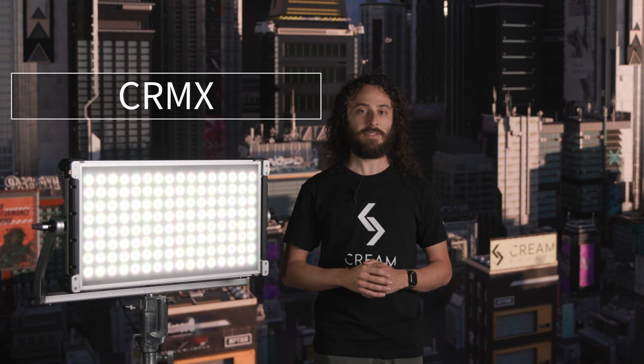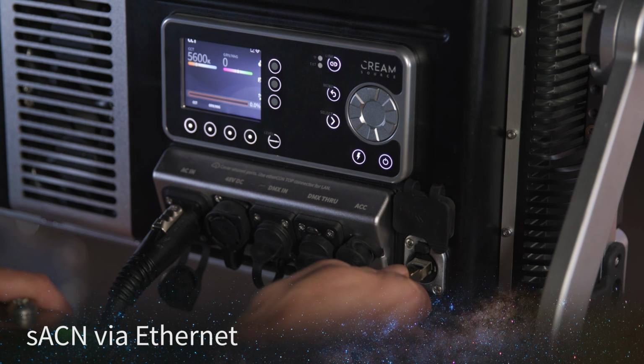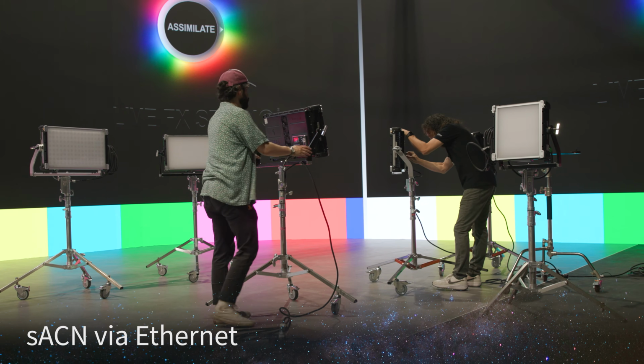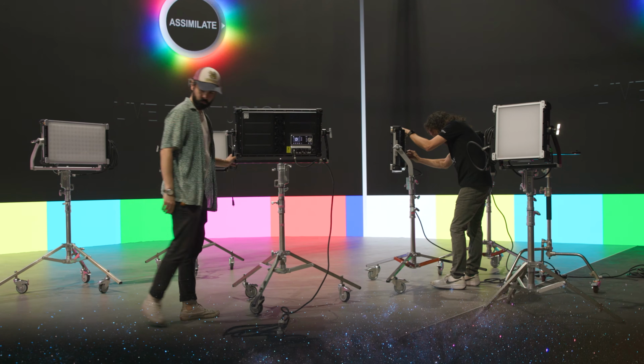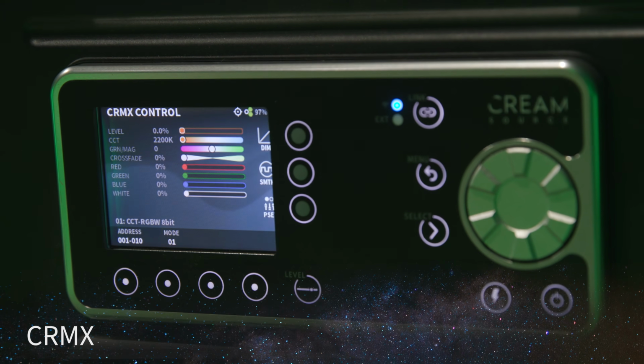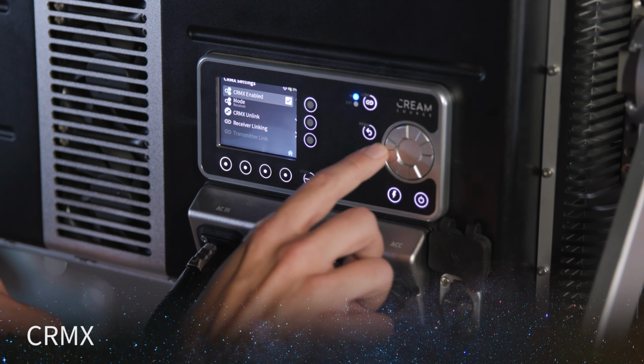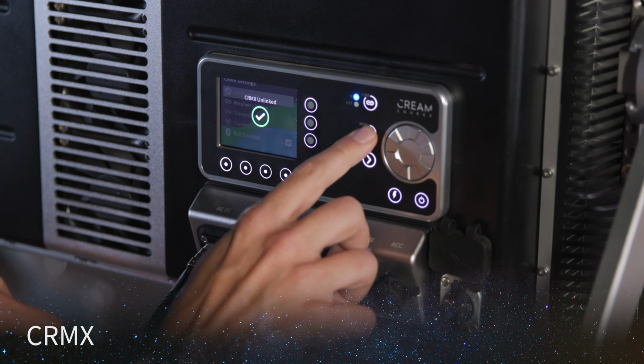When it comes to connectivity, you've got 3 main paths: streaming ACN via Ethernet, CRMX, and simple DMX 512. Ethernet allows you to plug straight from your media server into your switch, then into your fixtures. Quick and simple, and you've got fast, reliable data with no surprises. CRMX is your wireless solution, great when you can't run cable or need flexibility on set. Connect your CRMX transmitter to your network, ensure your fixtures are unlinked, and then hit the link from the transmitter.